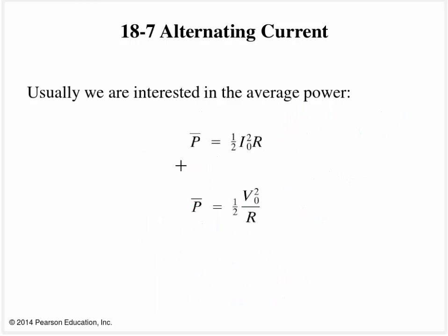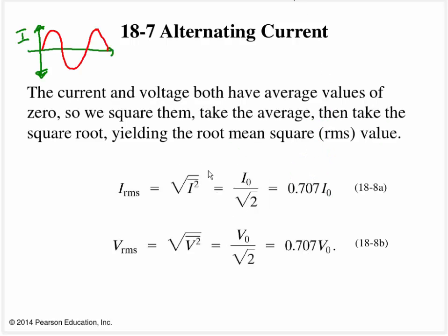So once again, we're typically interested in the average power, got a little ahead of myself there, which is just going to be 1/2 of the current squared multiplied by the resistance. And again, this is for AC only for both of these two guys.